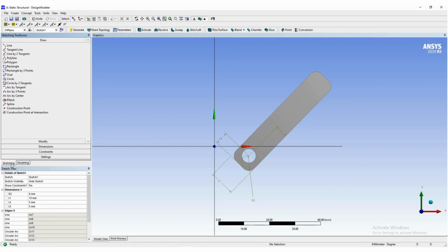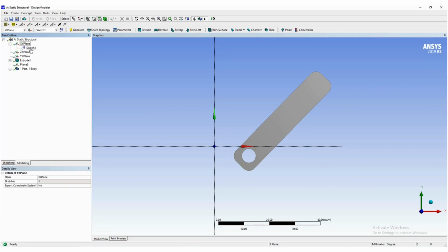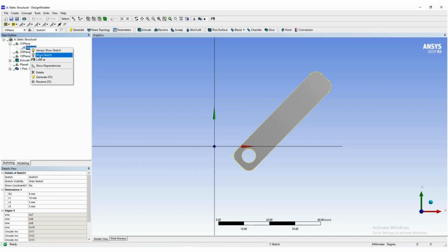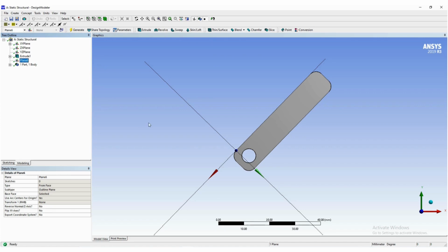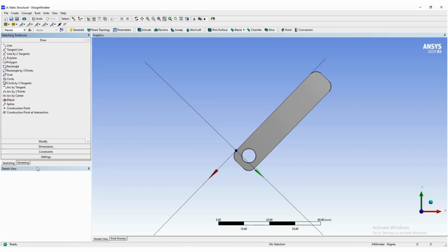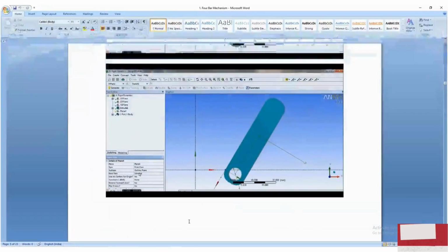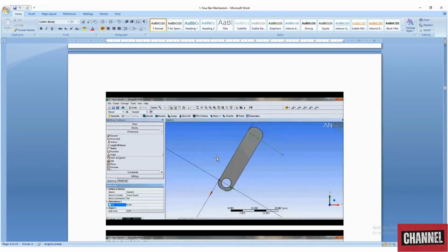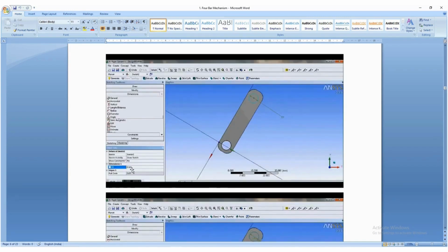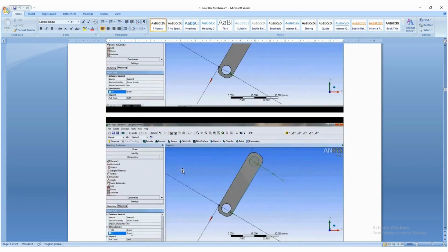Okay, now if we go here, we have our sketch option. So this is our hidden sketch. Now we'll just minimize this one, and we'll go on to plane 6. Okay, now we'll go in sketching. I'll draw one circle over here, simple circle. Now here, if you see its diameter, okay, that is d1, it is 6 mm we have to give. Okay, so 6 mm, and this length, simply that two dimensions we need to give here.